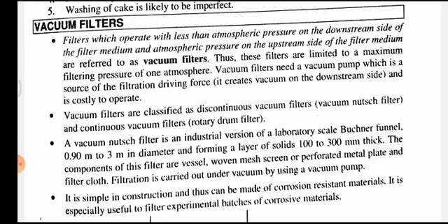These filters are limited to a maximum filtering pressure of 1 atmosphere. Vacuum filters need a vacuum pump, which is the source of the filtration driving force.